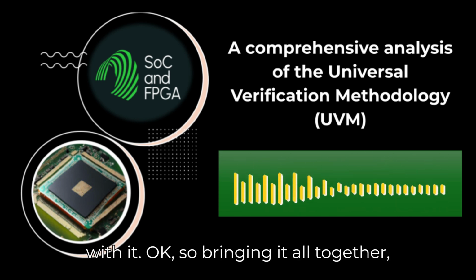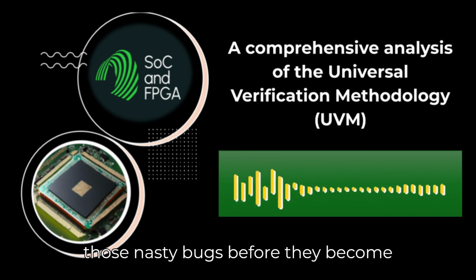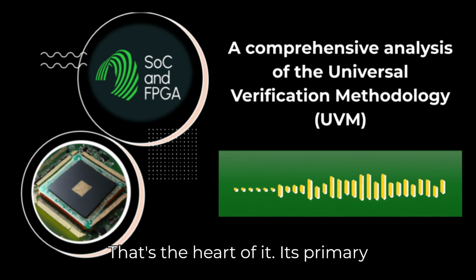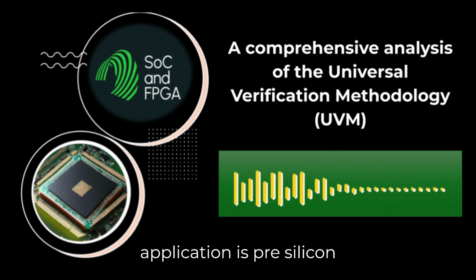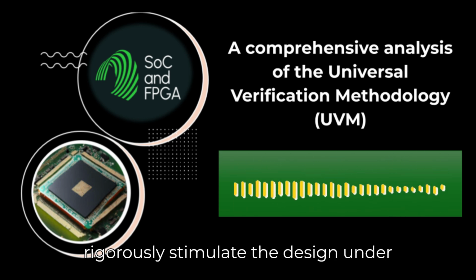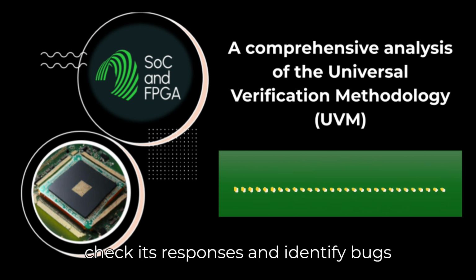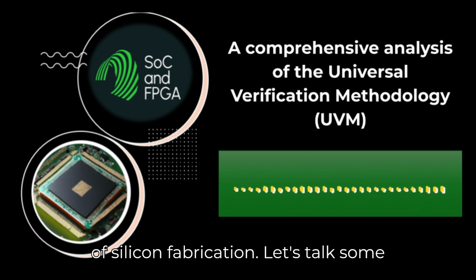Okay, so bringing it all together, UVM's core purpose is basically finding those nasty bugs before they become incredibly expensive silicon problems. That's the heart of it. Its primary application is pre-silicon functional verification. You build these comprehensive test environments to rigorously stimulate the design under test, the DUT, that's the actual chip logic, check its responses, and identify bugs before you commit to the costly process of silicon fabrication.